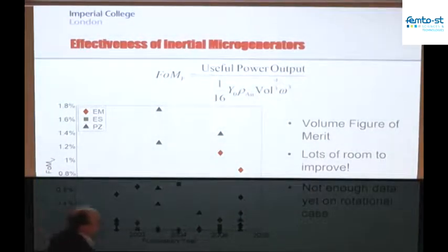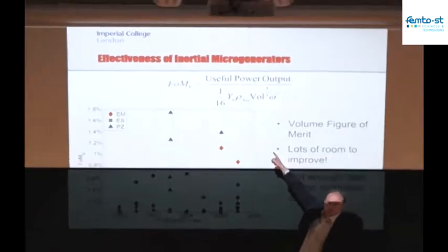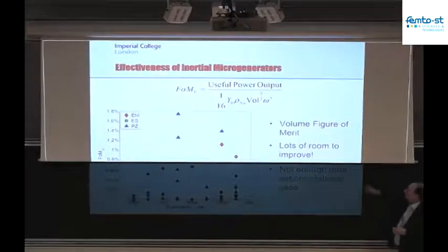So effectively, if you think about what I'm doing, I've got a mass that's moving inside a frame and it's going to be moving somewhat sinusoidally, and the strategy that we saw earlier was that I should basically design it such that I make exact use of the complete motion inside the frame. And if you look at that as being the kind of ultimate limit, then you can do a calculation straight away and you can say, well, that's actually the maximum power based on the density of the material I use for the mass. That's the total amount of power that I can generate with a sinusoidal movement inside a box of a specific size with a particular volume.